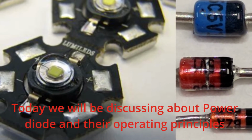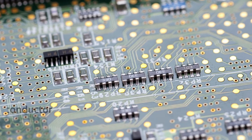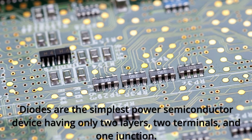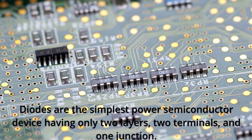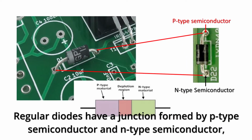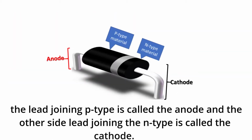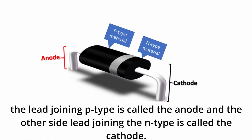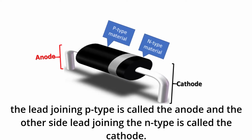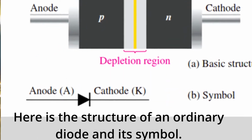Today we will be discussing about power diode and their operating principles. Diodes are the simplest power semiconductor device, having only two layers, two terminals, and one junction. Regular diodes have a junction formed by P-type semiconductor and N-type semiconductor. The lead joining P-type is called the anode and the other side lead joining the N-type is called the cathode. Here is the structure of an ordinary diode and its symbol.